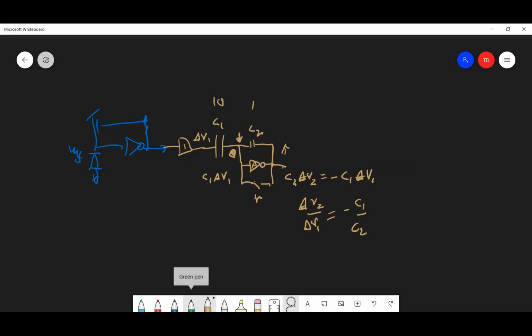And then how do you detect that the output voltage has changed by more than a threshold? Well, that's easy. You just put a couple of amplifiers there, like comparators, right? So you can put two comparators here. Let's just draw them like abstract circuits, like this. And then we'll put inside there a threshold function. We'll make one have a positive threshold, and the other one have a negative threshold. And this point right here in the middle is the reset point.